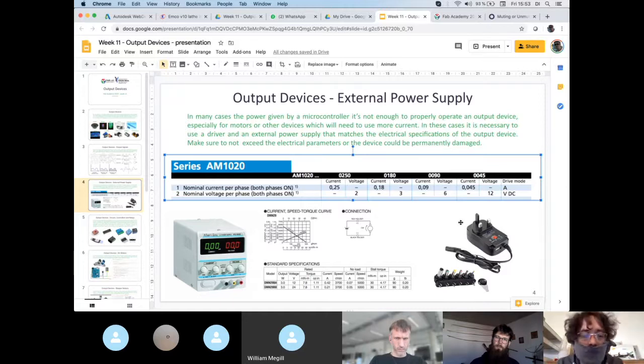In this case, something that you can do is power everything from one main source. So is the case, for example, maybe William with your Spider robots, or Hannes with your DPV system. Therefore, what you could do is transform this input energy source to the voltage that you need to power the microcontroller. In this case, you can use, I don't know, a step-down voltage regulator or voltage dividers, according to the current and the voltage that you need.